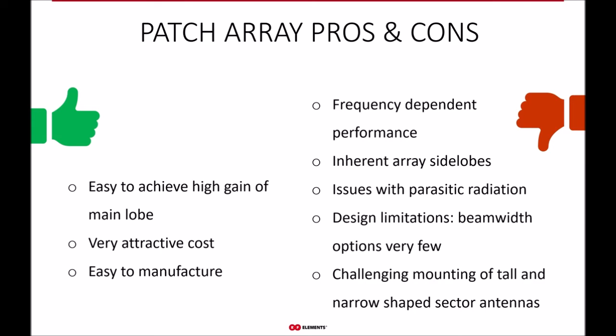should be mitigated. Also, the thinking that higher gain equals better performance kind of falls apart in the face of those high noise levels. One should really use an adequate gain antenna for the given job. Otherwise, you're hurting yourself and actually also others at the same time.